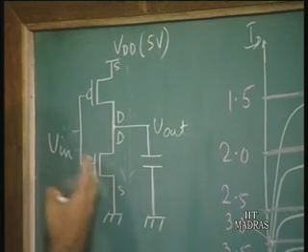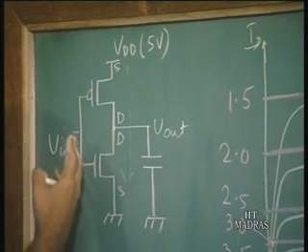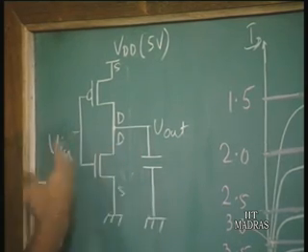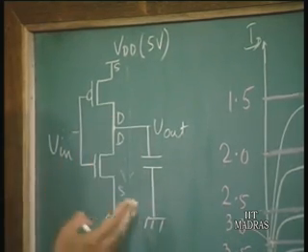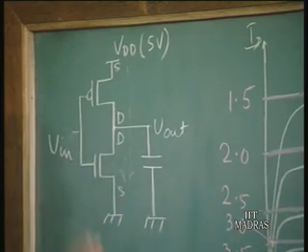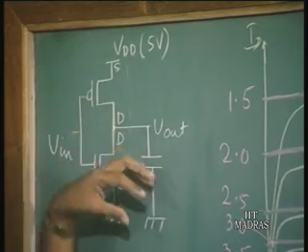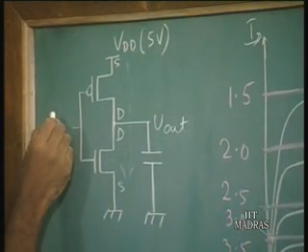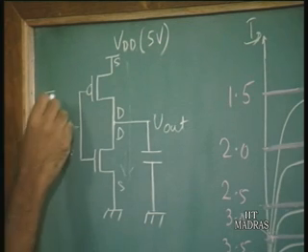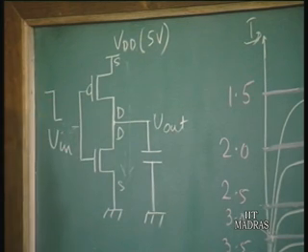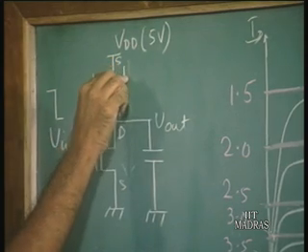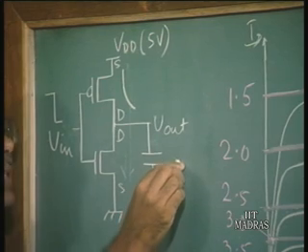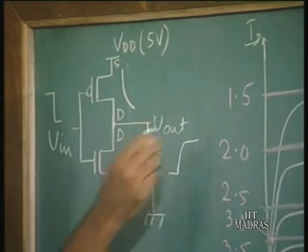Since it is a CMOS, we know that the input resistance is extremely high. So there cannot be a normal current flowing in the normal static condition, but because of the presence of the capacitance, there will be a current flowing, basically to charge or discharge the capacitance. Now, suppose the input is high, and it makes a transition from high to low. Where is the current flowing? The output voltage was low, and it has to go high.